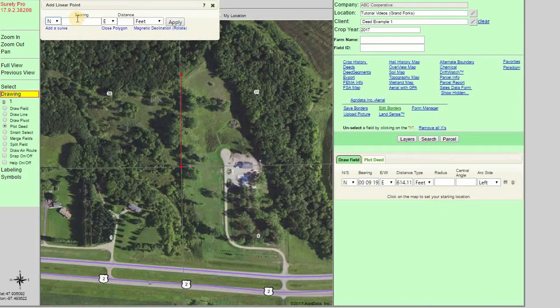And we'll just continue to create these lines based on our legal description. So north 53 degrees, 30 minutes, 50 seconds, again east, and for a distance of 232.62 feet. So this kind of continues until we get to our curve. So I'm going to bump this along here, and I'll join you back in a second.